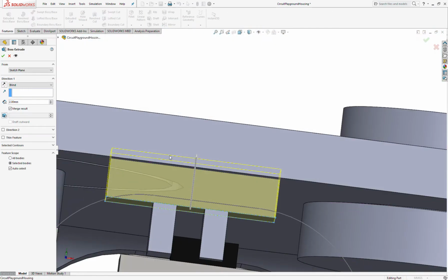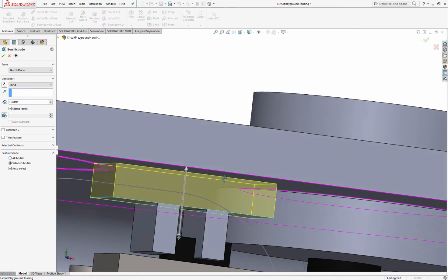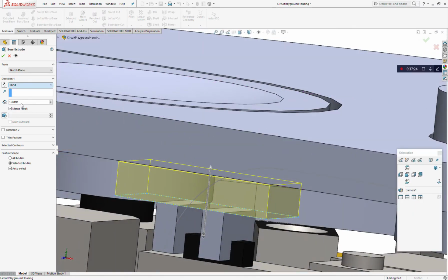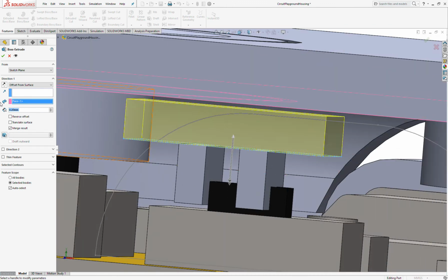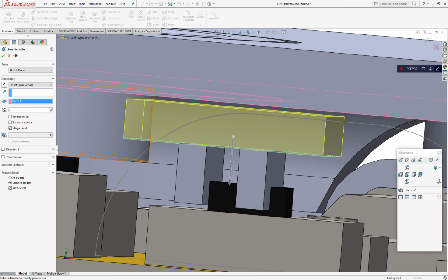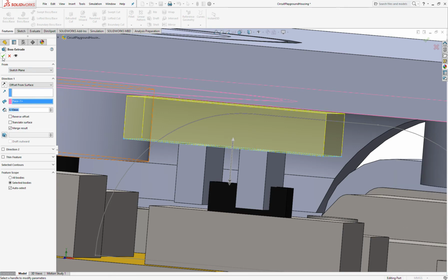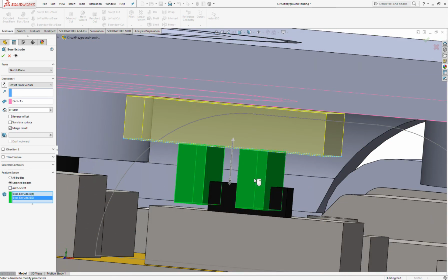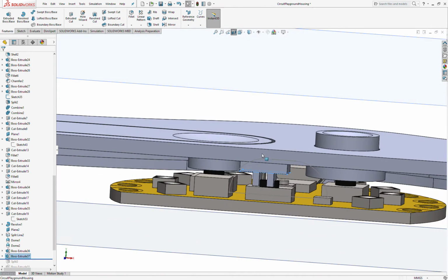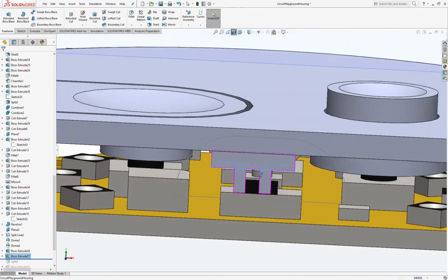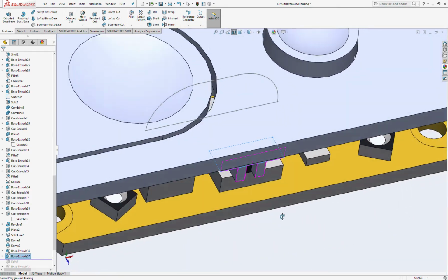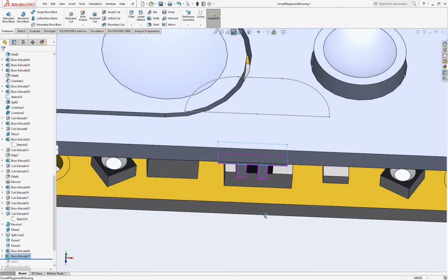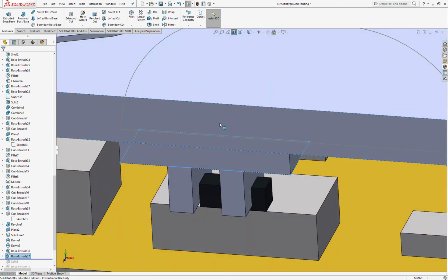Now we're going to extrude this up, and we're actually going to extrude it up basically just offset slightly from the bottom, by like 0.2. Maybe 0.1. We're going to merge the result, but with these two. Alright. So, making progress. So now we're going to add the top of our switch. So we really want to be on the top surface there.